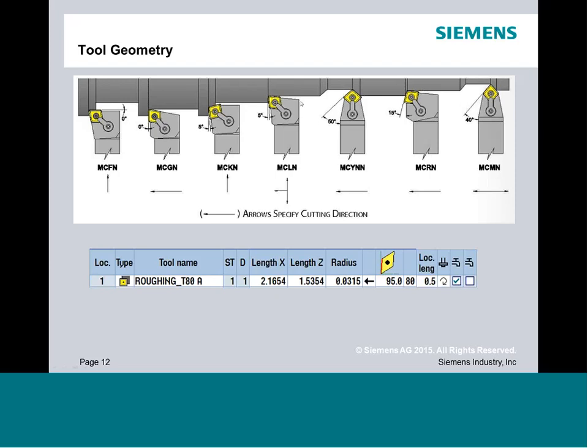If I don't, and I send a tool into an area, like you see this little groove here, where it potentially can't fit, if we don't know where the back is, we could crash that tool, or we just wouldn't go in there at all. And what we want to do is use as much of the tool as we possibly can when machining a part. So that's where this all comes into play. We're going to start to explore how this physical tool sits in the pocket, and then where I feed that information within the standard description of a tool in our system.